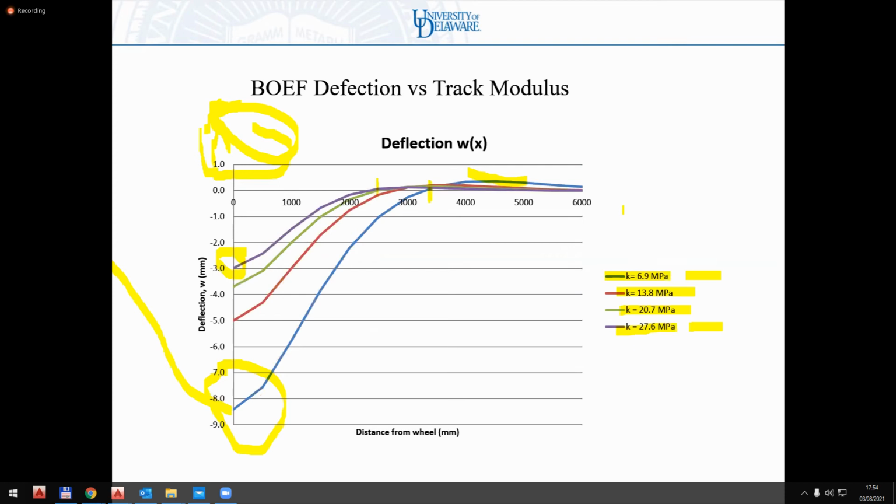In fact, the track stiffness is a very major effect on the distances. So if I have a very stiff track and it's a 2 meter effect, then more than likely the second axle of the same bogie will be important, but the next bogie of the adjacent wagon is not going to have an effect.